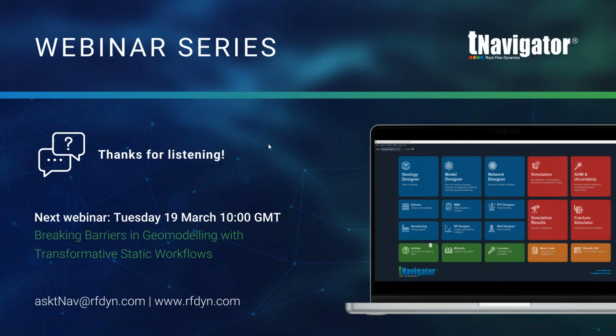The other algorithm that we have available is the critical stress intensity factor. In this case, the mode 1 stress intensity factor needs to be higher than 1 minus the breakdown criteria tolerance multiplied by the critical stress intensity factor. The frac growth criterion and the crack criterion tolerance are specified by the user in this case if the second option is being selected.